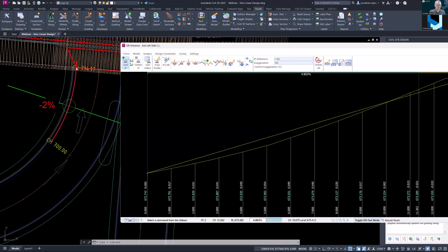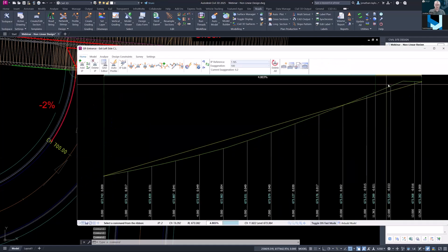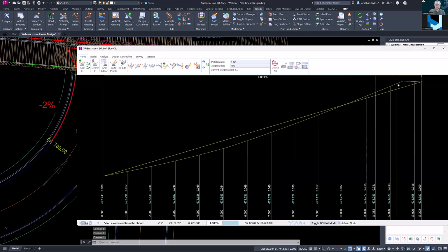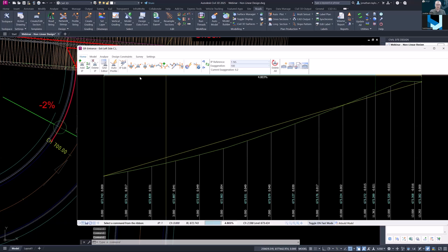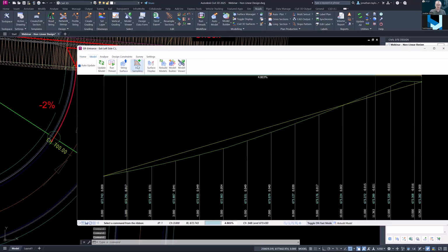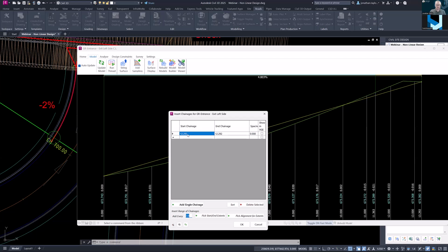The only thing I've had to do here is because I have no sample at this particular location, I've actually introduced one on this particular grading string. What you'll notice is that as we take this grading string up to the boundary, I've got no sample line here, which means that if I wanted to perform a constraint or some kind of match, I need a sample position in that spot. So if I go to the Model tab, add sampling, I've added a sample onto the boundary.